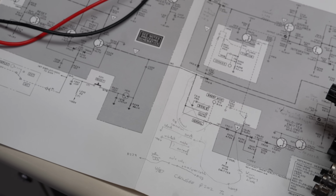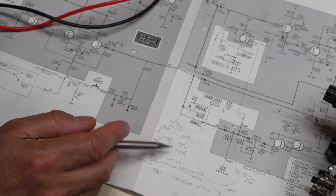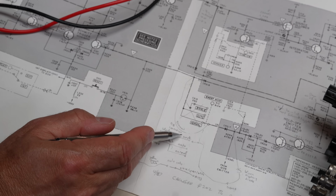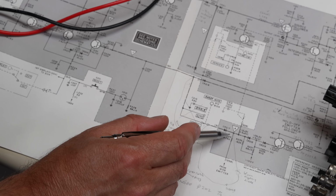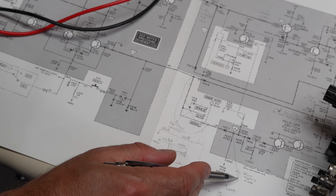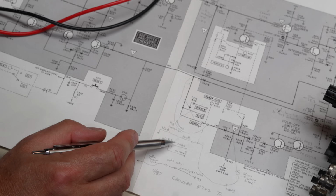On my revision it's not wired at all, as they say. None of that is used, so instead you have a contactor that uses this diode, and in single mode it grounds it, so that disables this point, that puts it at ground. In normal and auto it's connected to minus 100, and this diode will just not be there. It will not be conducting, and it will have the regular circuit and it will go through the permanent connection.